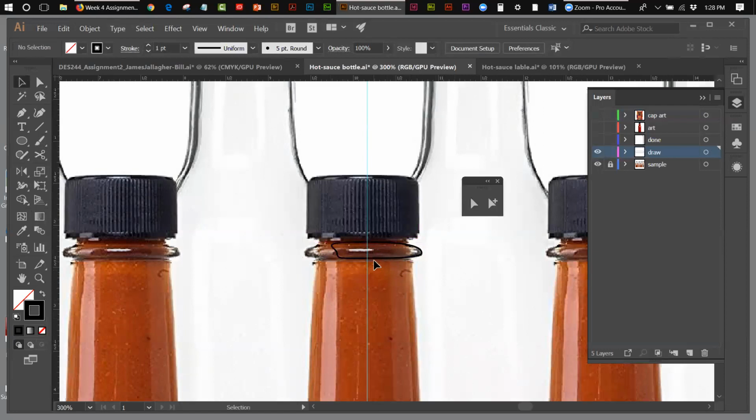So what I want to do now is I want to cut this shape to this line. Everything is going to get cut to this line because I'm creating profiles for everything. So I need everything to be cut to the same position, which is that line right there. So I'm going to select this. Once again, get the scissors tool, and I'm going to carefully come in here, and I'm going to click and cut that line. And then I'm going to come up here, and I'm making sure I'm sitting right on my guide, and I'm going to click, and I'm going to cut that.